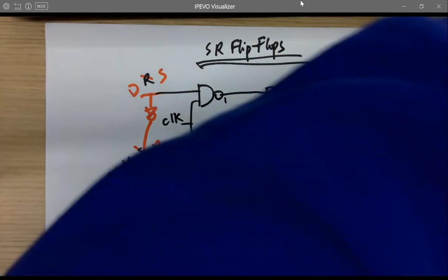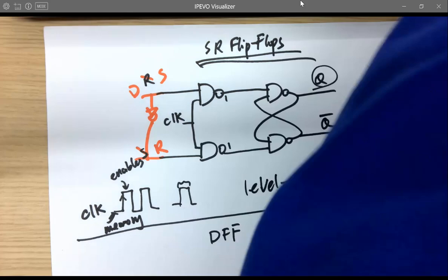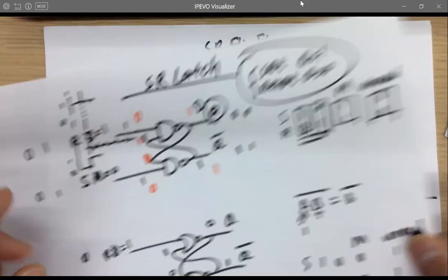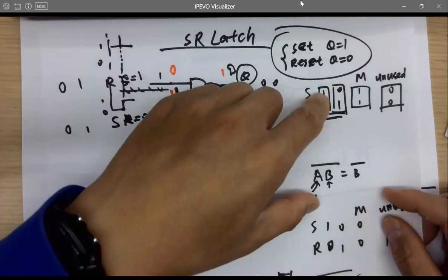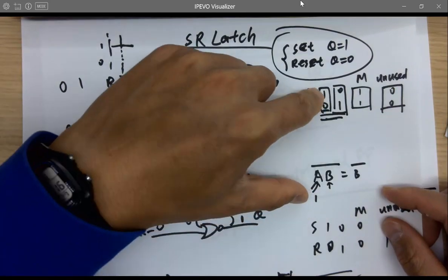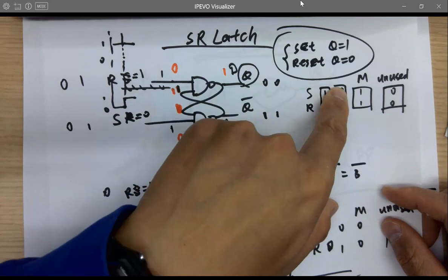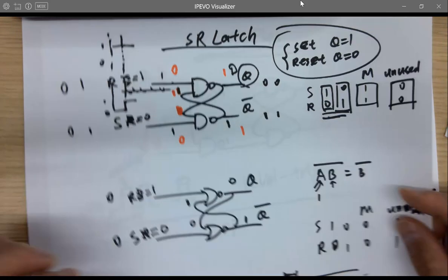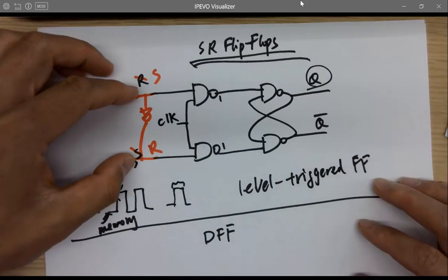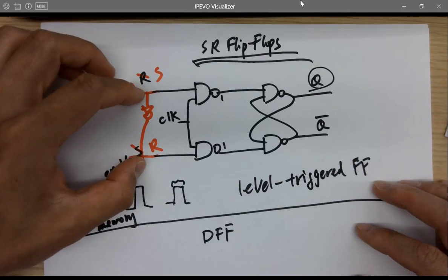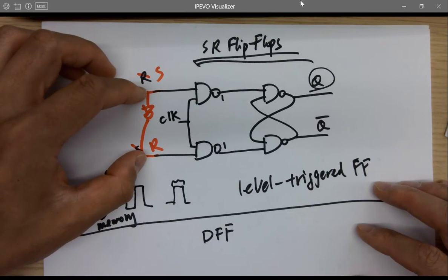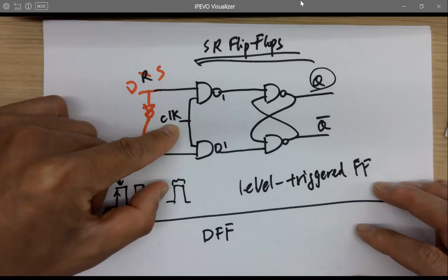And the reason we put an inverter here is because remember the states when we use it. Okay, the inputs are inverse, right? If one, the other one has to be 0. If one is 0, the other one has to be 1. So that's why we just lock it in that state, the two states. So you're never getting both zeros and both ones. It's not really memorizing by the inputs, but it's memorizing using the clock, right?